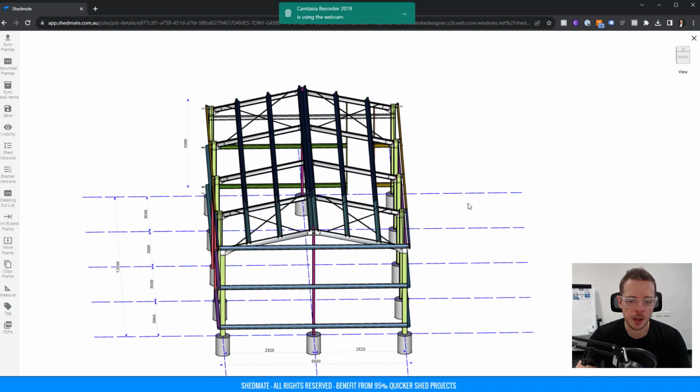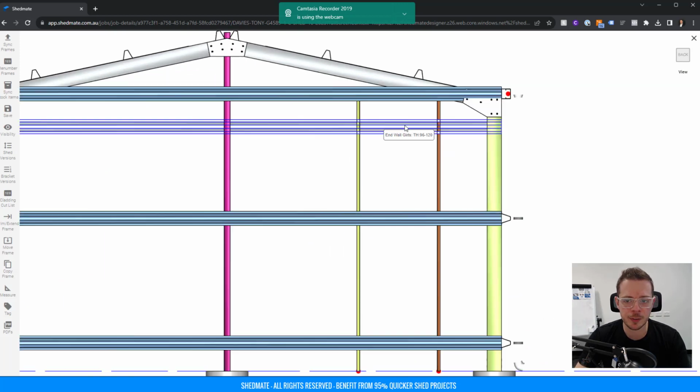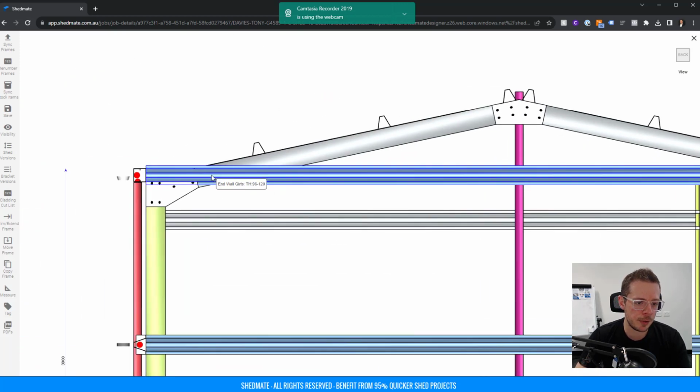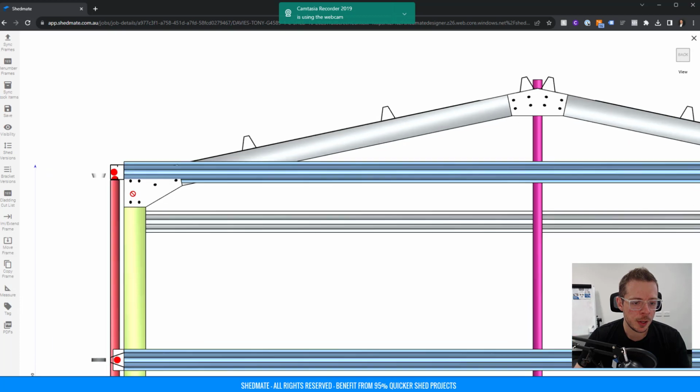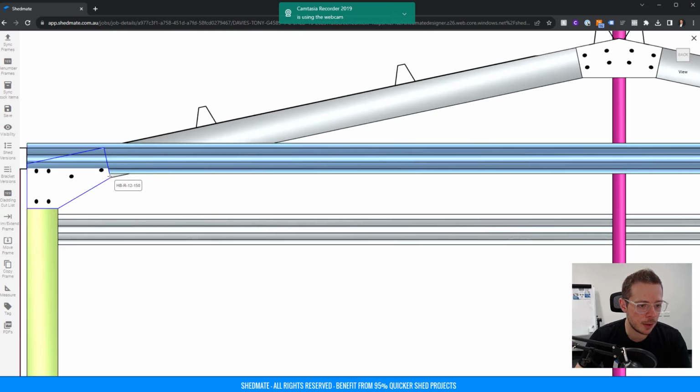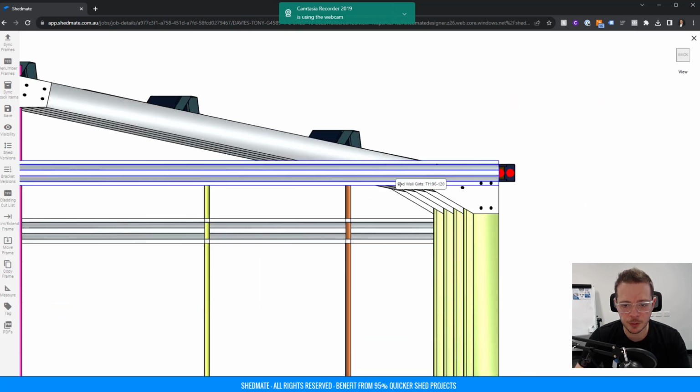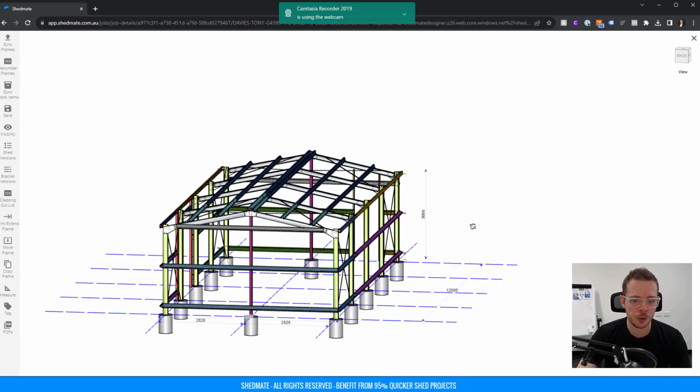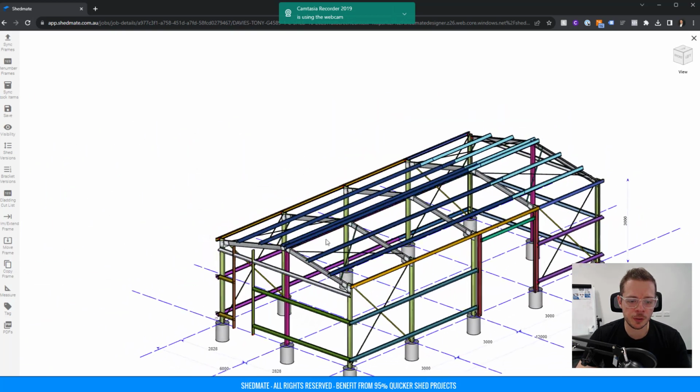If I go to the other side, I'll just do the same, but using a different setting. So some people, they just leave it as it is, but they will cut this a little bit. So what I can do is I can actually trim it, and I'll just add an additional extension here and trim it like 50 mil, hit go, and I'll select this item and that line of the bracket. So it cuts 50 mil from there, and I can do the same here. This item and the bracket, done. So these are just two different ways of doing the same thing.